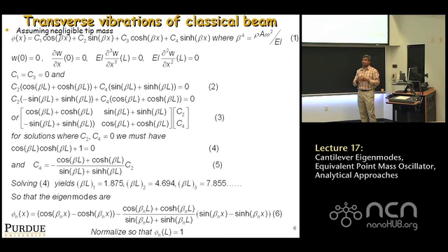Okay? It just means that this beam, therefore, supports an infinite number of discrete frequencies at which it has this characteristic shape. It's a resonance, okay? And for every beta value, if you do it, you actually get the lowest value of beta times L as 1.875. The second value of beta at which equation 4 is satisfied is 4.69.